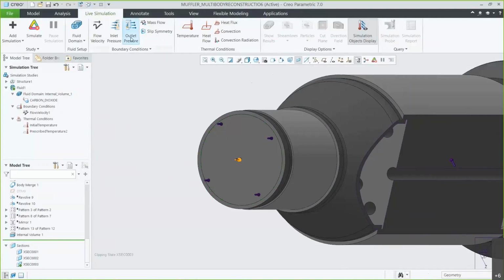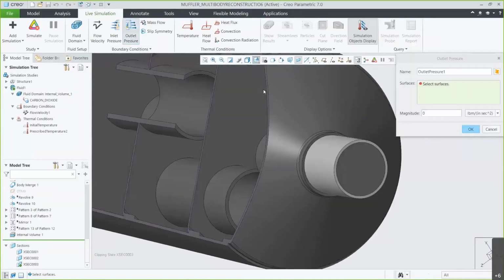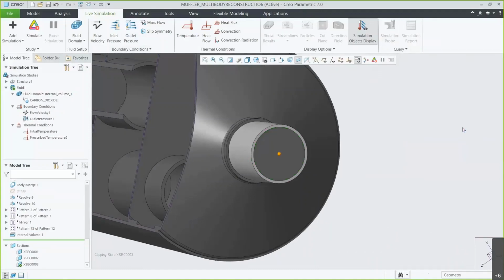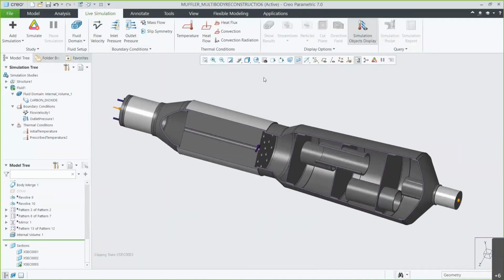I'm pretty happy now with some of the initial conditions I have at my inlet. So next I'll also define down in my outlet some of the pressure for my motor. So moving around to the back end, in my case, I'll just simply set it to 0, essentially just outside air there. With that, I'm pretty much ready to jump into the study.